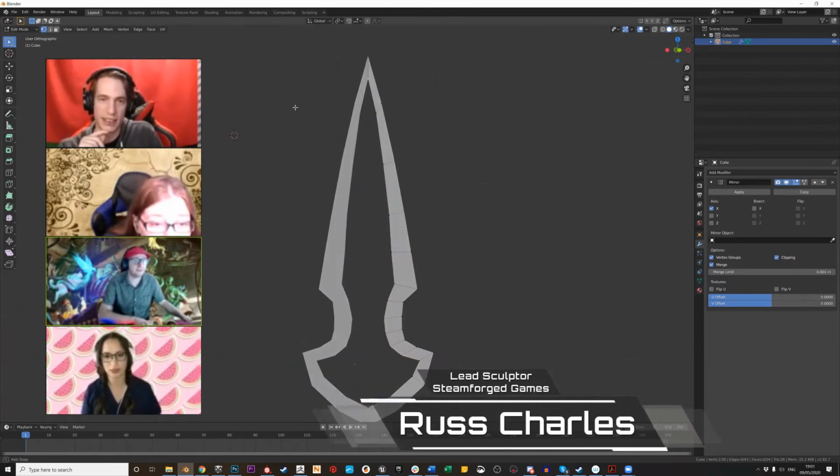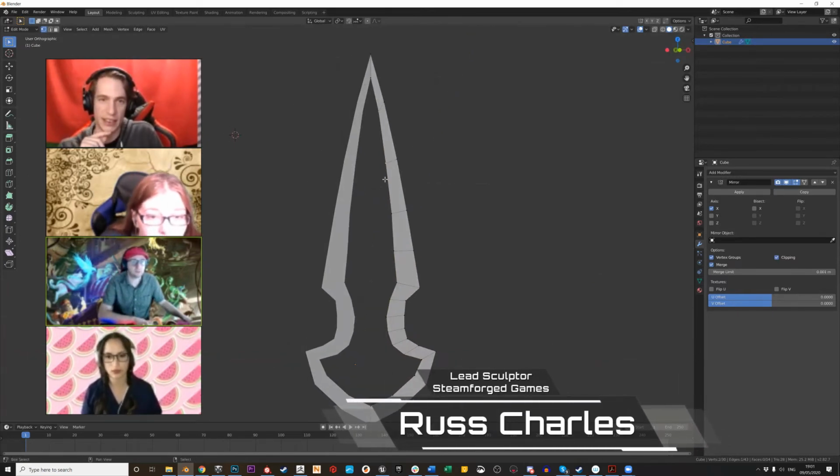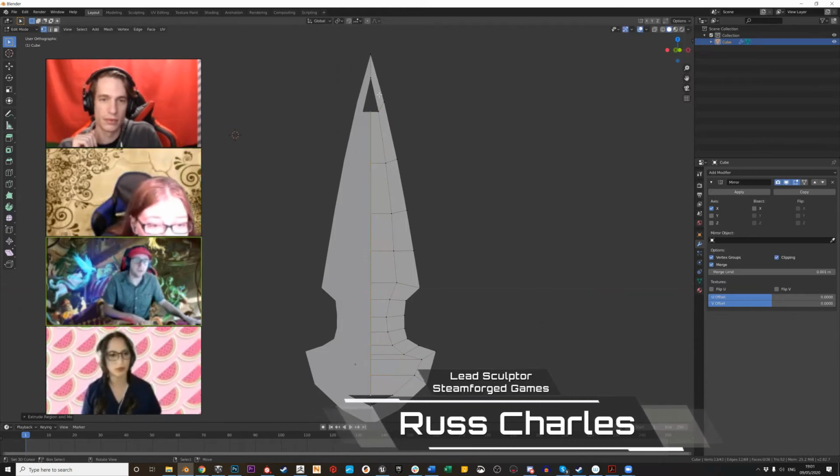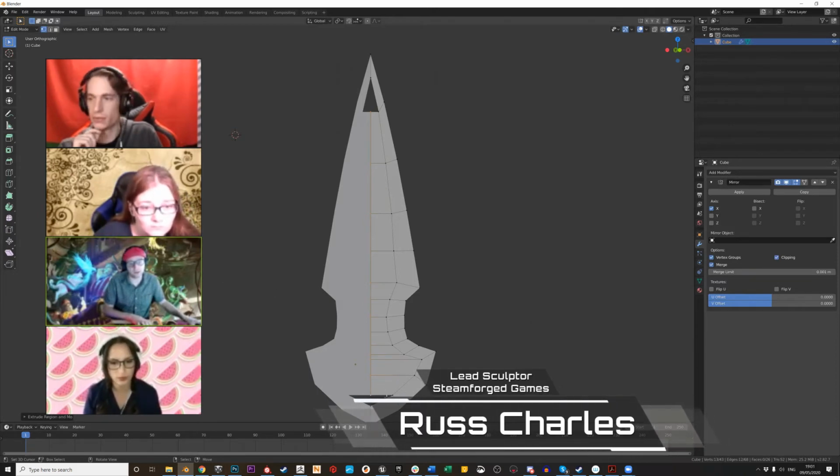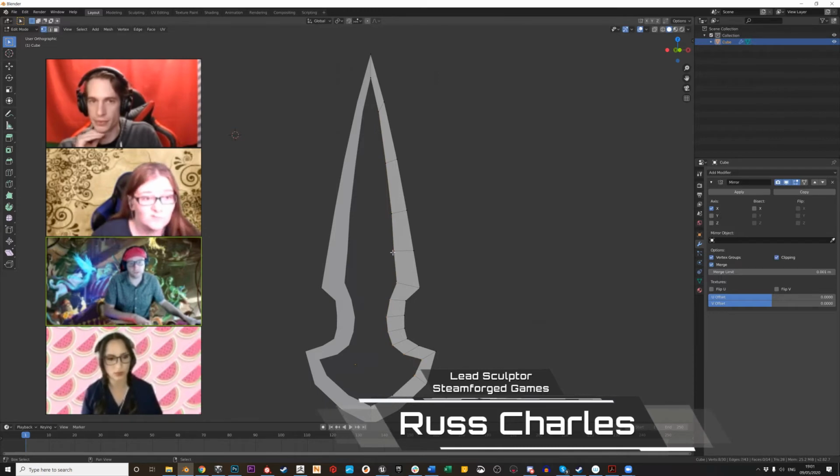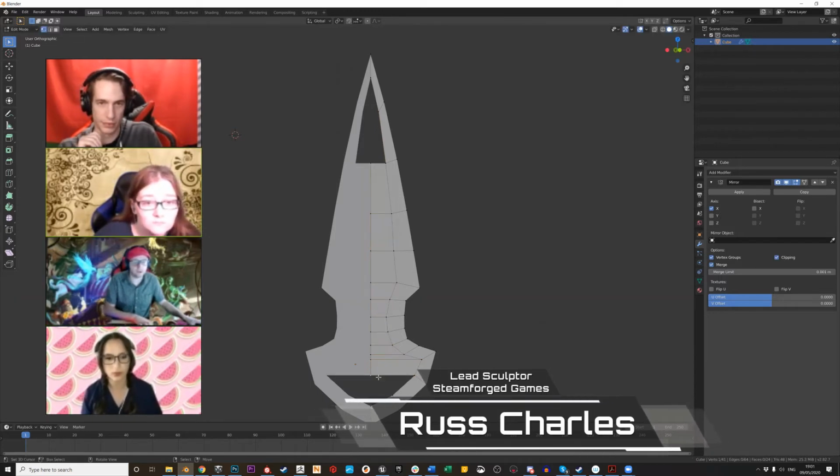We'd never select that top one anyway because it's already at the center. So if we selected all of them and didn't worry about leaving that gap, X, I end up with a triangular shape at the top and the bottom, and that's going to cause us a problem later. So basically, we're avoiding that triangular shape by extruding in such a way that we only keep quads. Generally, you just have to remember triangle's bad.